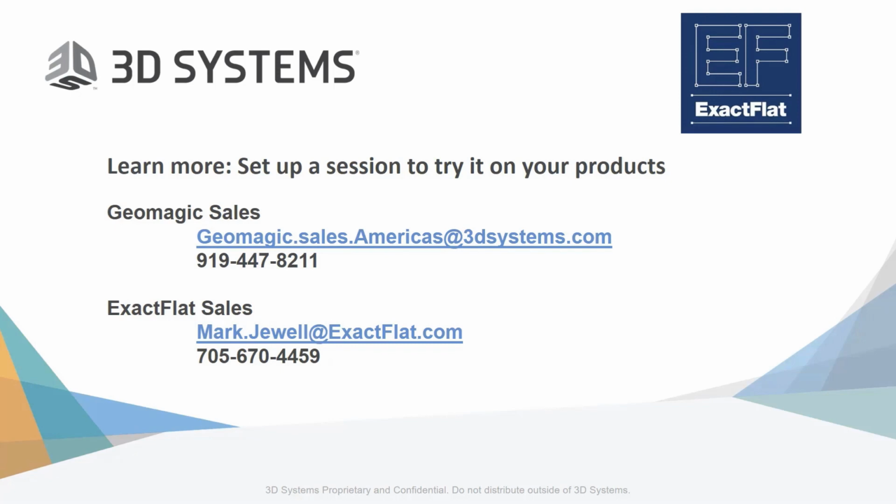We have another question. If I'm working with a material which is not in the ExactFlat database, how do I add it? This is a very good question. So ExactFlat comes pre-populated with some of the most common materials for some of the most common products. But if you're working with a material that you might have engineered or one that just does not happen to be in the ExactFlat database, you can add it very easily. There are two ways to do it. If you know the engineering characteristics of the material in question, that is Young's modulus, Poisson ratio, stress limits, elongation limits, you simply go to the ExactFlat material manager, and you enter those variables in the fields that are there.